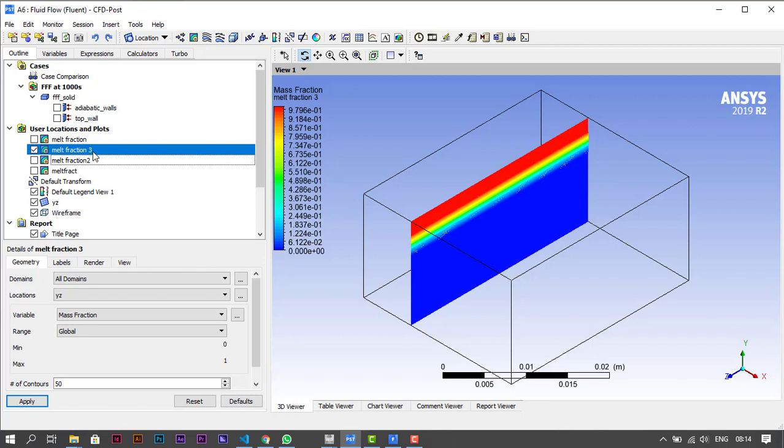So now if we want to create a plane which is across, a horizontal plane, I'll show you how to do that right away. The key we need to take note of is this general coordinate. So we have the y-x, so we should know that any plane we are creating in the y-x coordinates will be something around this way. We have zx, okay, so the horizontal plane is zx. So once we check this, we can know the plane we're working with.